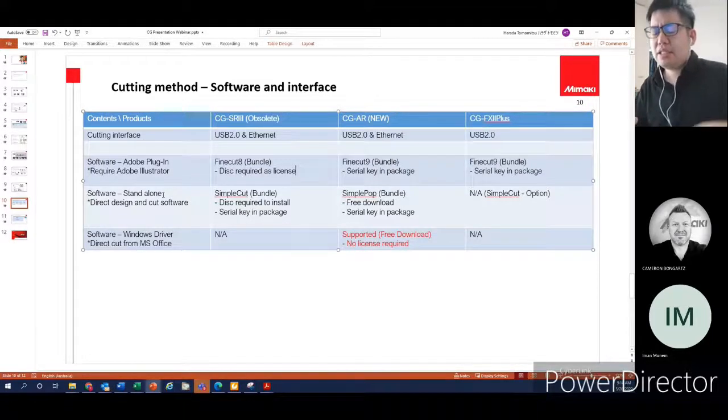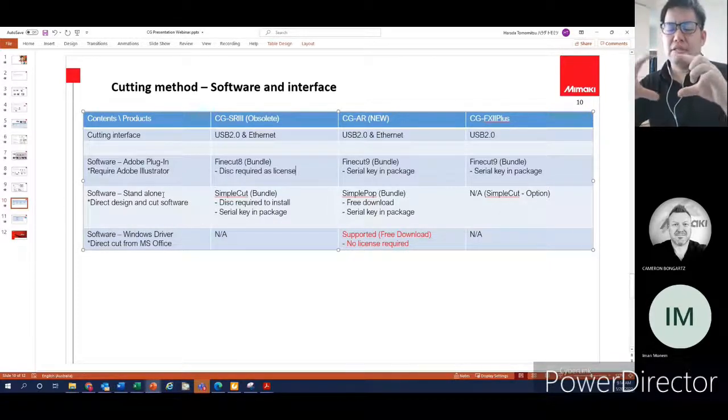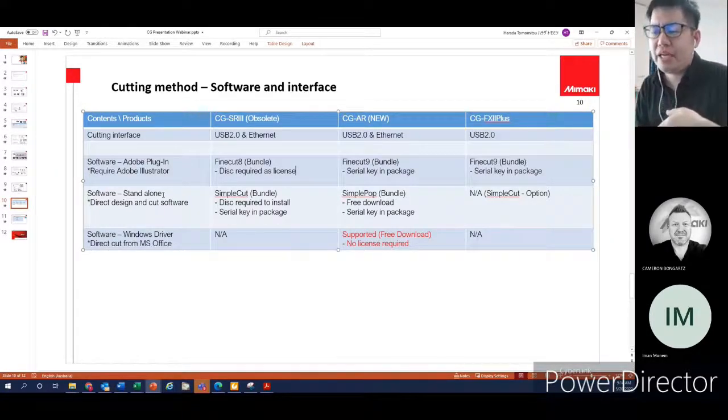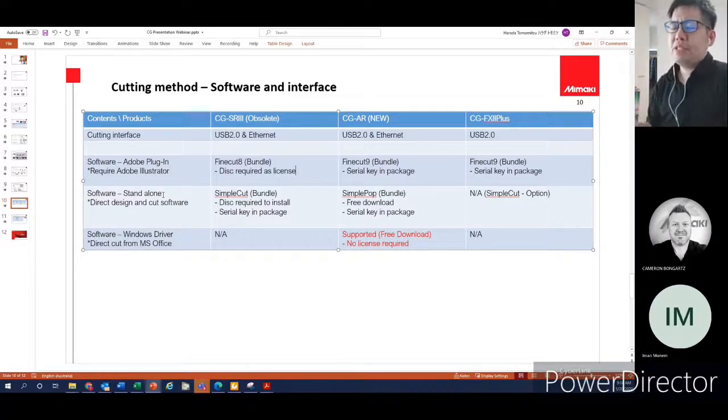However, mostly you need to bring a bitmap file or JPEG file for something to print, and then you manually draw the shape for the cut. So you can export to RasterLink for printing, and you can export directly to the cutting plotter for cutting purposes. So it's really simple, but it has very limited functionality.